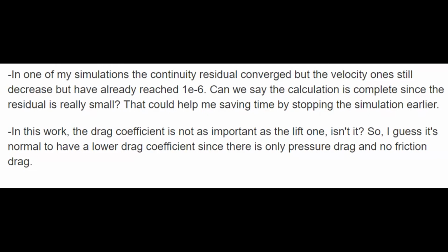Can we say that calculation is complete since the residual is really small? I already answered this question today in the Moodle, but I can confirm that we usually consider flow converged when the residual is smaller than 10 minus 4.